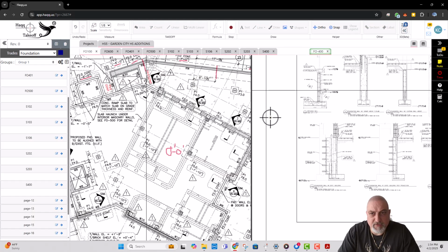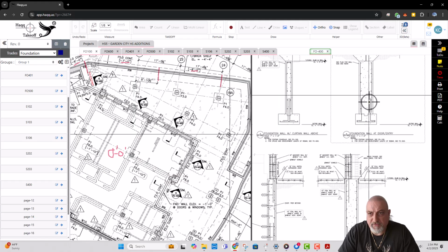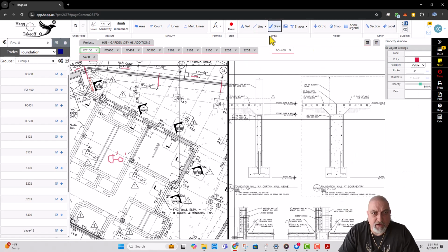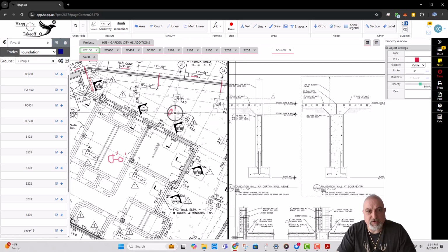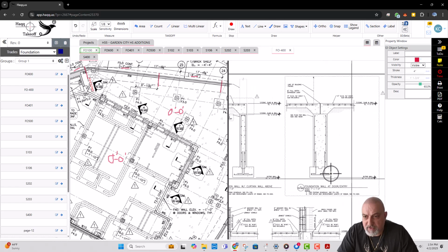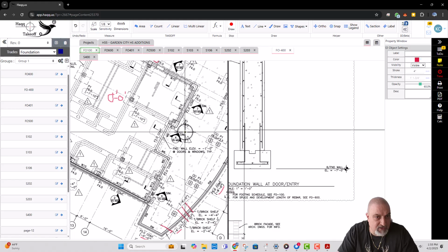And let's split this to the right. So we're looking for the section 4, 7. Section 4 show top of slabs are equal. So top of slab is here. Let's highlight this back. Make it an active window. And elevation is 0 as well. Top of slab elevation. How about the bottom of footing? Does it give you bottom of footings? Yes, -7. This is -7 in brackets. This is your bottom of footing here, and the same details here. So we got -7 feet in the brackets, bottom of footing.